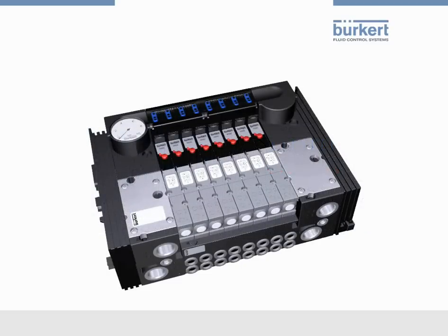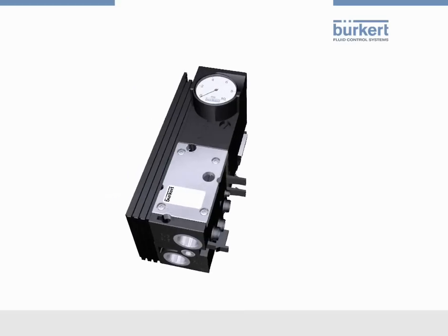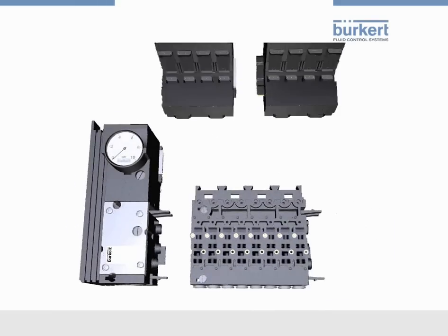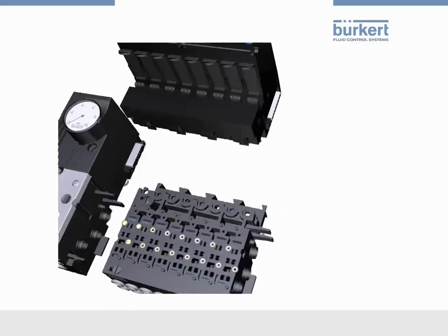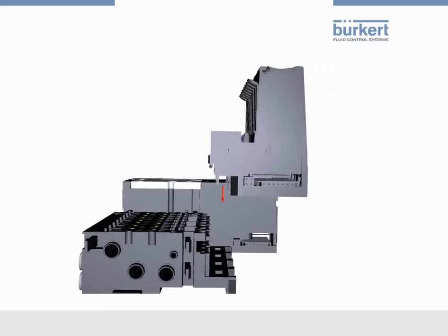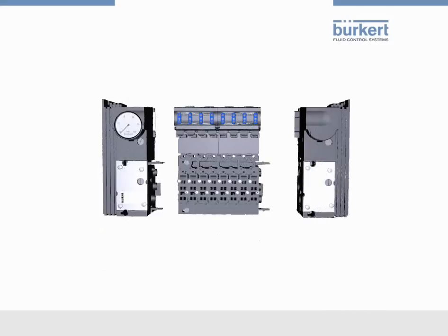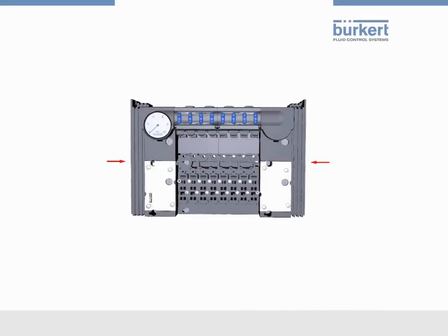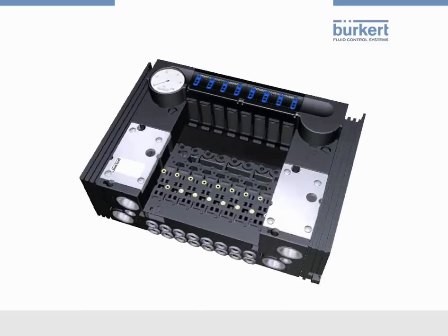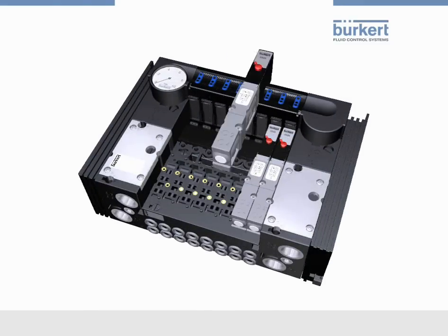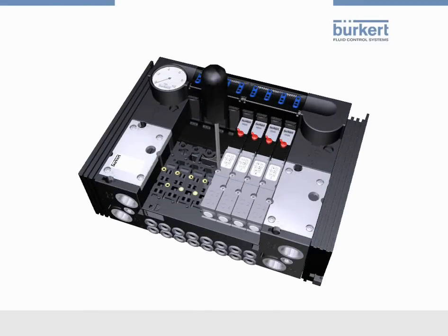The pneumatic parts of the airline are constructed in a similar way as Type 8640. We'll take a look at the left supply module, which ensures both the pneumatic supply of the automation system and the interface to the I/O modules of the cooperation partners. The pneumatic and electrical basic modules are connected to one unit and mounted together with the left and the right supply module. In the last step, the valves are mounted on the automation system.